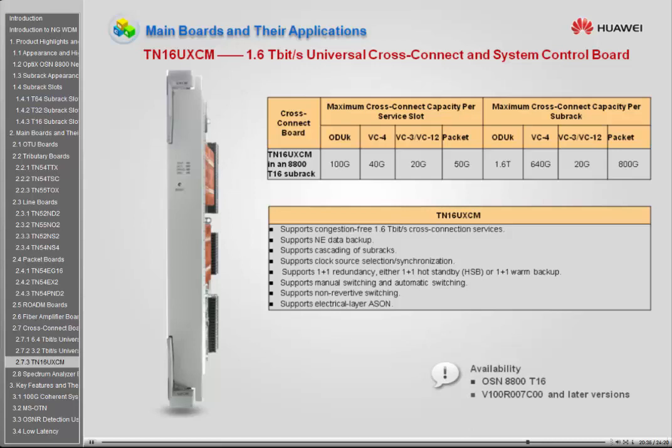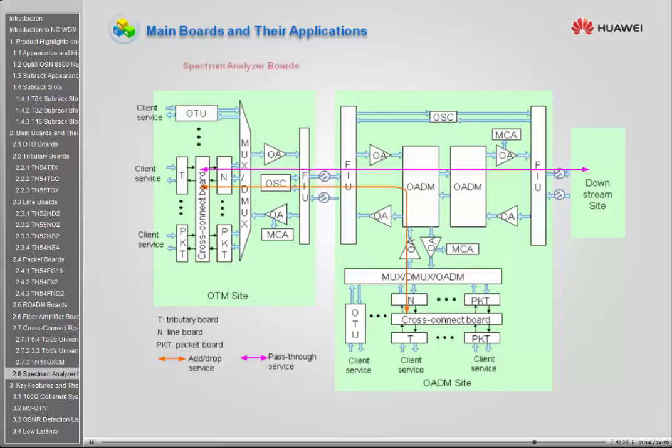In addition, by collaborating with the U2000, this board manages all other boards inside an NE, establishes communication between the resident NE and another NE, and provides the NE with a physical clock or PTP clock for the clock synchronization purpose.